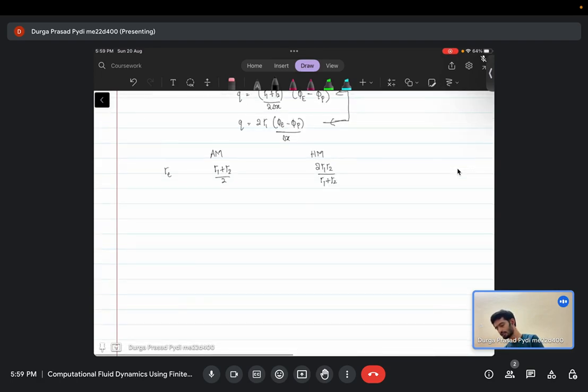So you have an insulator towards your right, so essentially I am saying gamma 2 equals 0. So you have a material where this is your insulator, gamma 2 is 0. What does that mean? At this particular face, your flux going along this direction should be 0. There shouldn't be any flux inside the insulator.